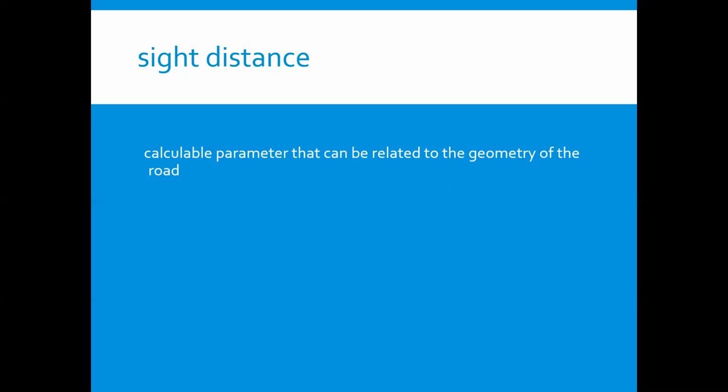The assumed parameter values lead to sight distances that produce a satisfactory design. Where possible, the sight distance provided should be greater than the values recommended in any guidelines. Adequate sight distance is essential for safety and efficient traffic operation. The designer should consider the lengths of vertical curves, the radius of horizontal curves, and the terrain on the inside of horizontal curves in providing adequate sight distance.